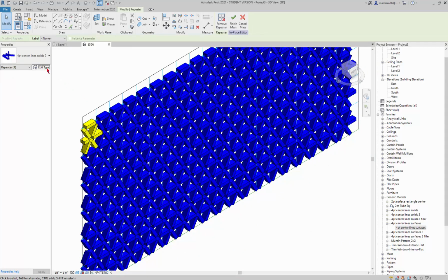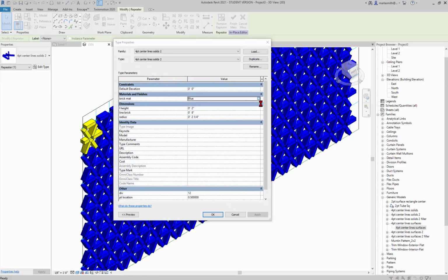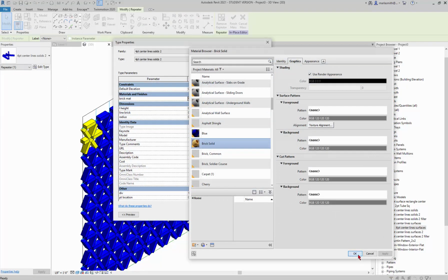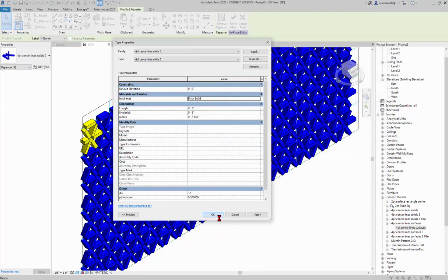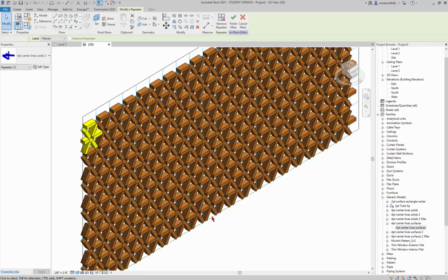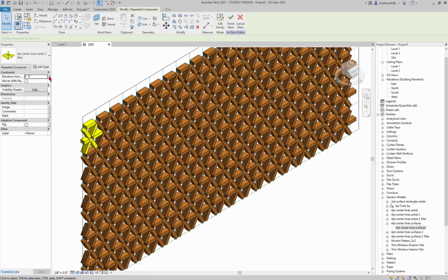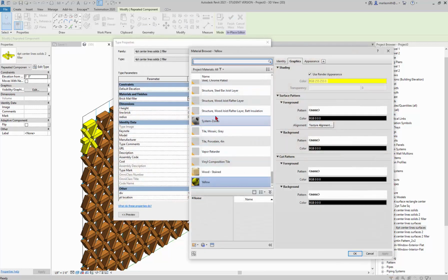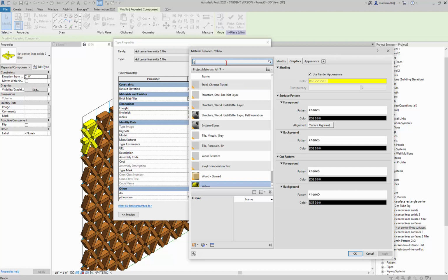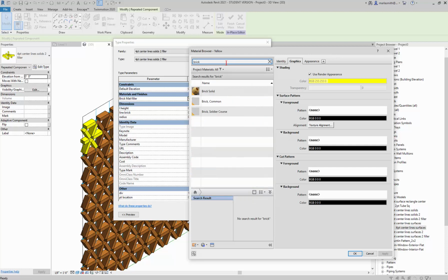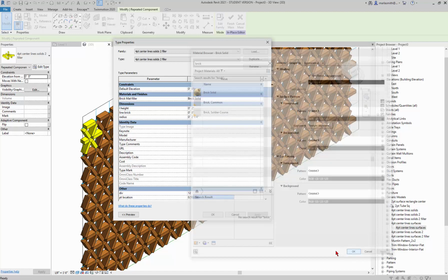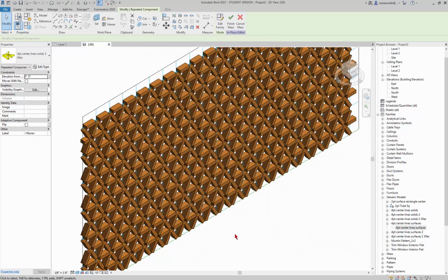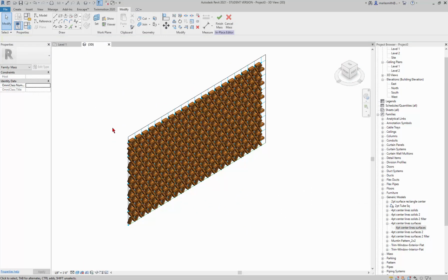Again, these guys, if you edit type, you should be able to update the material for them, right? So, except for the ones that you've put in uniquely, you'd have to do those individually. So, edit type and fill that in with the brick, right? Individually. Okay. And then you kind of have your wall. Once you're done in here, you click Finish Mask.